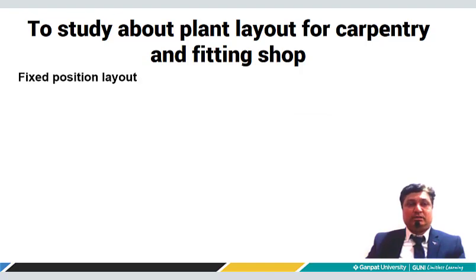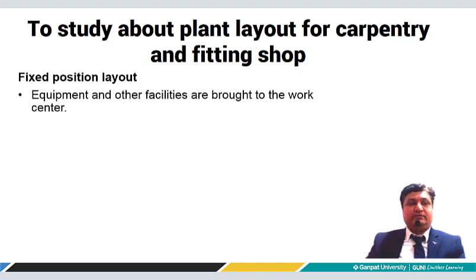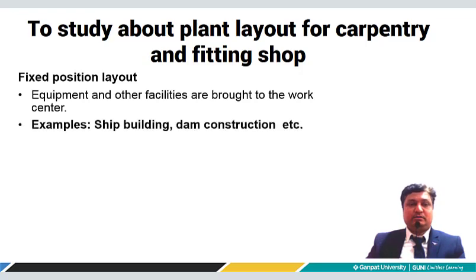Now the fixed position layout. In a fixed position layout, the equipment and other facilities are brought to the work center itself. For example, shipbuilding, dam construction or spacecraft construction. The main advantage of this type of layout is that we can reduce cost according to our customization.